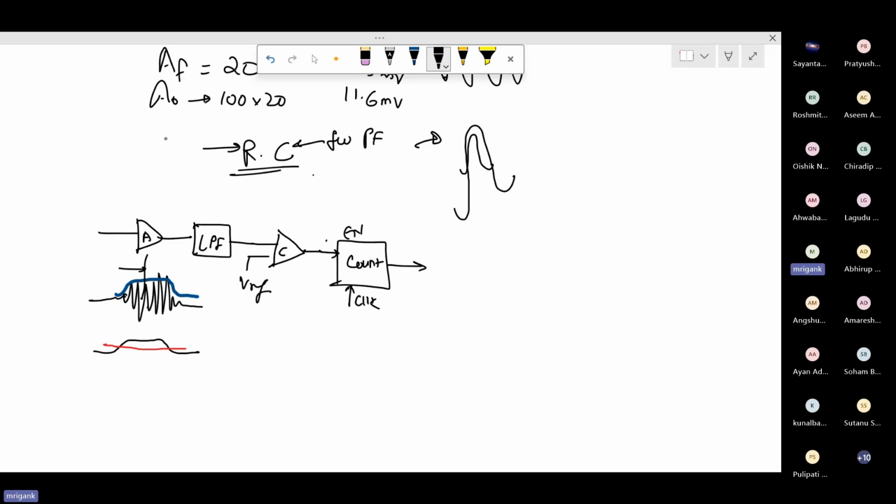And then based on that, you can make a single order or second order low pass filter. But again, the R will not be very accurate, because the R obtained through subthreshold resistance transistors is going to vary over process. So you have to make sure that we are able to tune it, and that it is not varying very widely. Those concerns will be there. So it is definitely introducing more challenges, because the LPF design will become more challenging, especially for very low frequency.